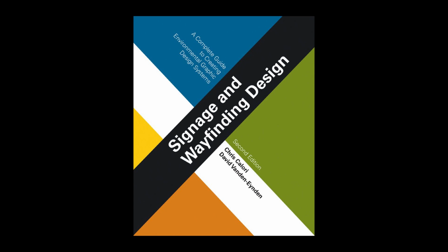In most cases, the submittals are stamped or tagged with a review stamp that has checkboxes for indicating the submittal's approval status. Typically, these boxes are labeled in a range from approved, outright approval, to approved as noted, conditional approval, to revise and resubmit, to rejected.